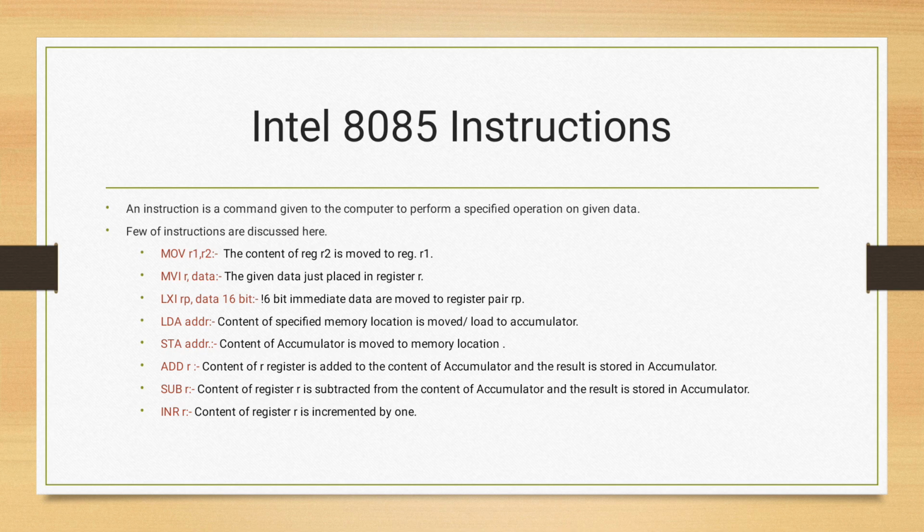Next one is STA address. This is the reverse of LDA address, which means the content of the accumulator is transferred to any arbitrary memory location. Next are ADD R and SUB R, which are categorized under arithmetic operations. If we take ADD B, the content of register B will be added with the content of register A, the accumulator, and by default the result will be stored in the accumulator. The same thing happens for SUB R.